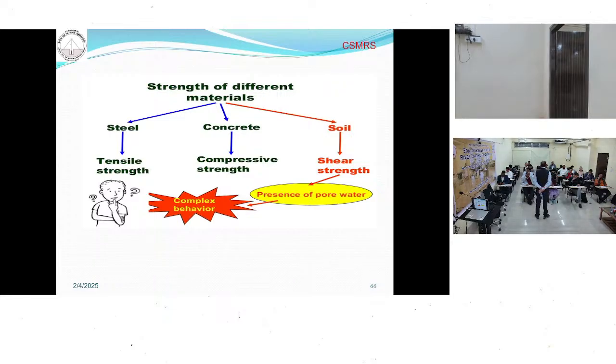Your office hours are maybe 8 to 10 hours, but the test continues for 24 hours. It might be that after 15 hours the settlement becomes constant, but you come in the morning, so we change the load in the morning. In the automatic test, it will find out that the settlement has become constant and change to the next load. In that way you can save some time.